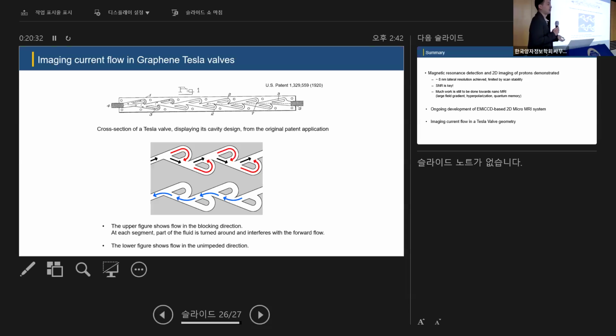Also, it highlights an excellent application of NV-based imaging. Two-dimensional materials like graphene are well suited for NV-center magnetometry because the NV layer can be brought into very close proximity to the active current channel.